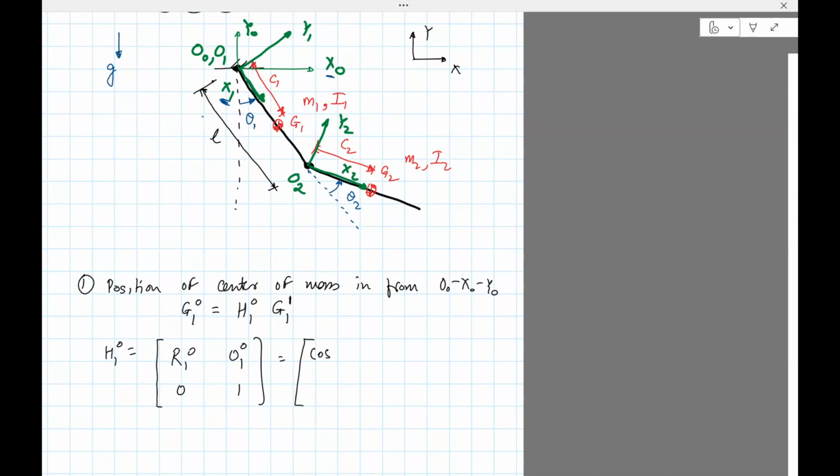Now, you can see that one way of computing that angle is going clockwise like this. Another way is to go counterclockwise. I would say that you should always stick to the counterclockwise convention. It makes your life easy. You could go clockwise, but then there are complications like clockwise is negative, and then you're always confused about signs and so on. So just do the simple thing, go counterclockwise, which is a positive direction.